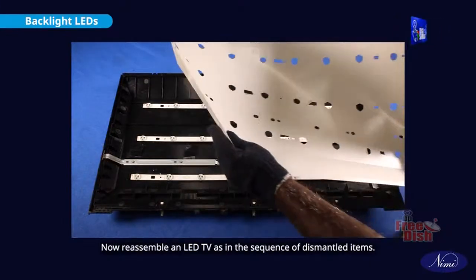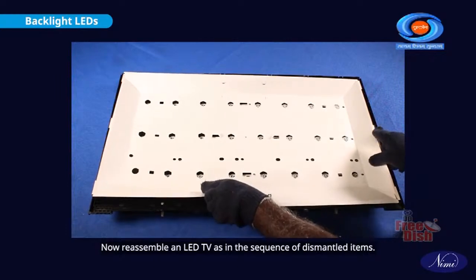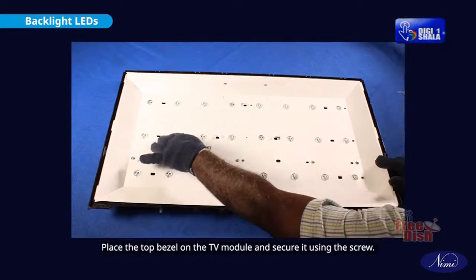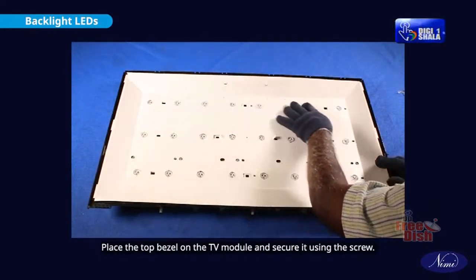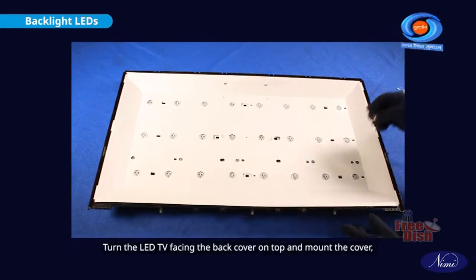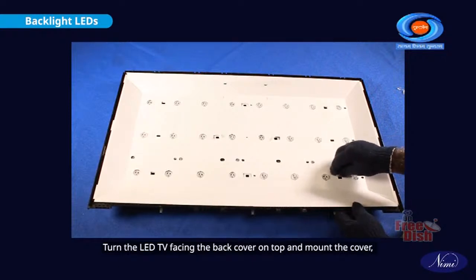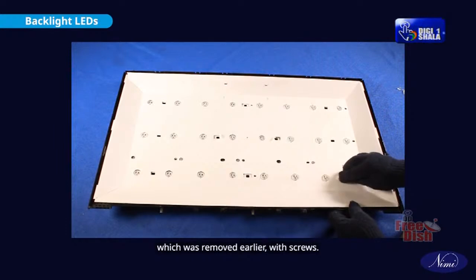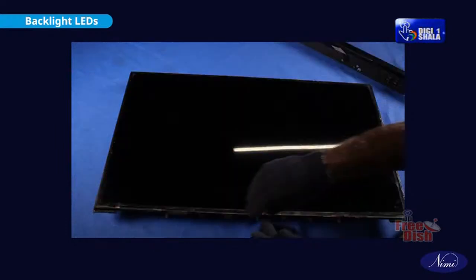Now reassemble an LED TV as in the sequence of dismantled items. Place the top bezel on the TV module and secure it using the screws. Turn the LED TV facing the back cover on top and mount the cover, which was removed earlier, with screws.